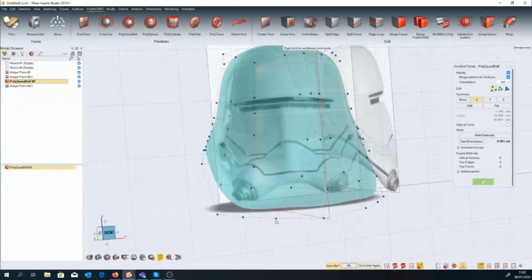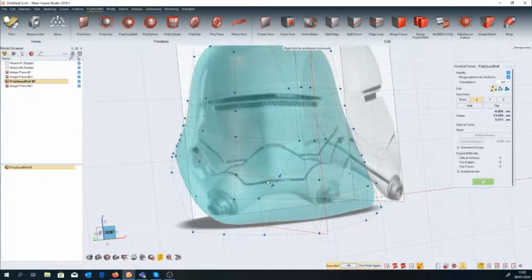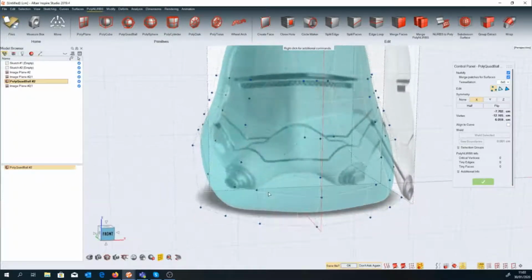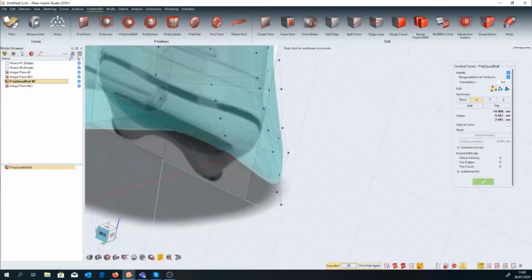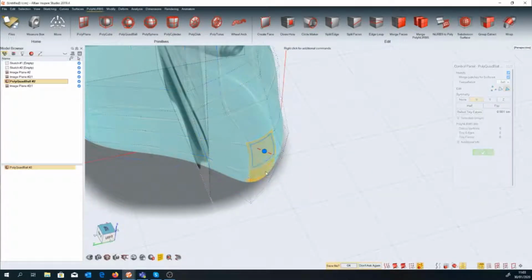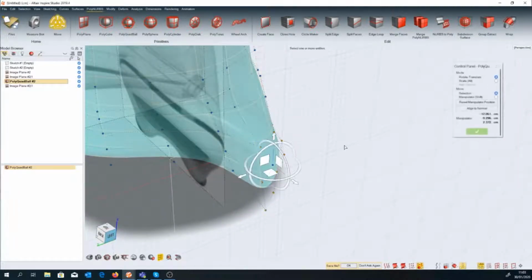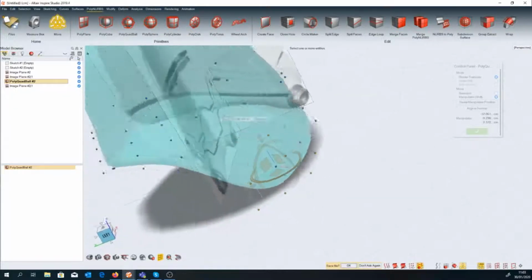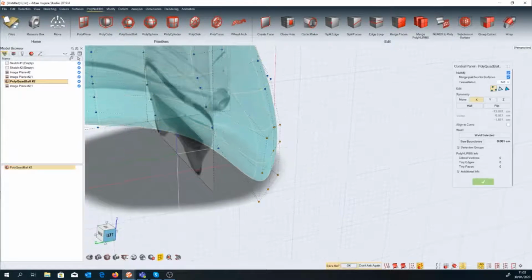The first step is the creation of a rectangular perimeter. To do this, I select and move some vertices. In the second step, I'll select all the vertices inside the rectangular perimeter, and with the Move tool, I'll scale them along a single direction with a value close to 0. Now we have a planar surface with a discrete tolerance of approximation.